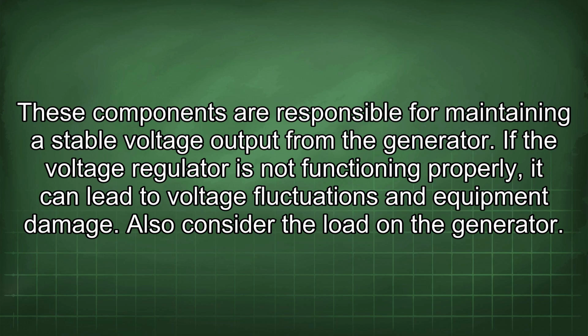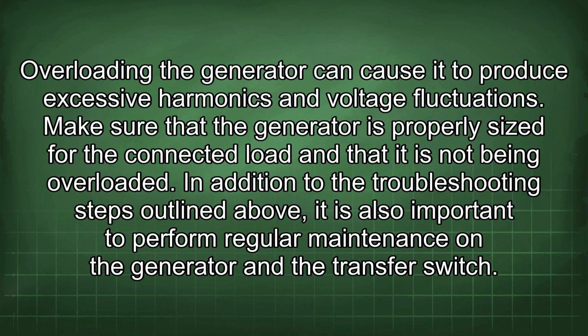Also consider the load on the generator. Overloading the generator can cause it to produce excessive harmonics and voltage fluctuations. Make sure that the generator is properly sized for the connected load and that it is not being overloaded.